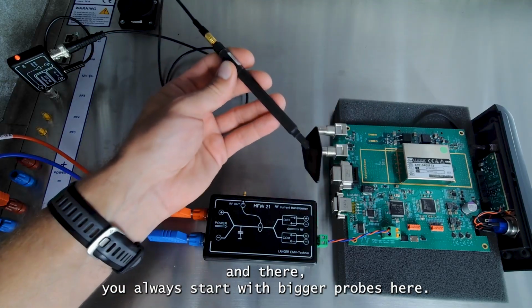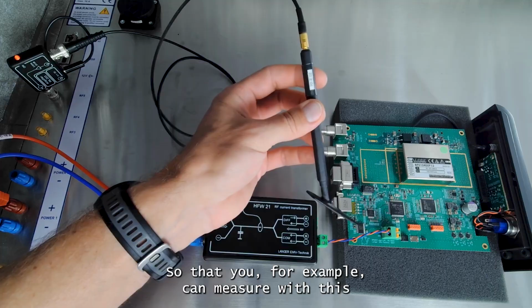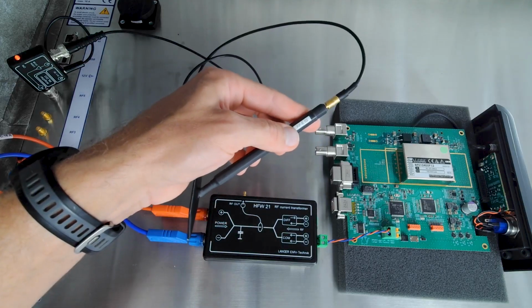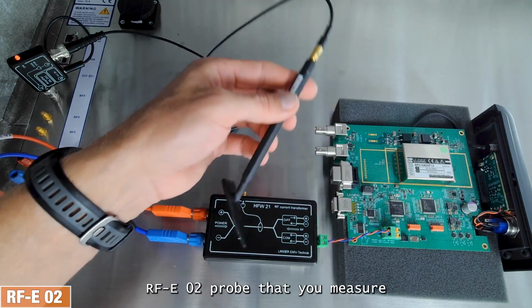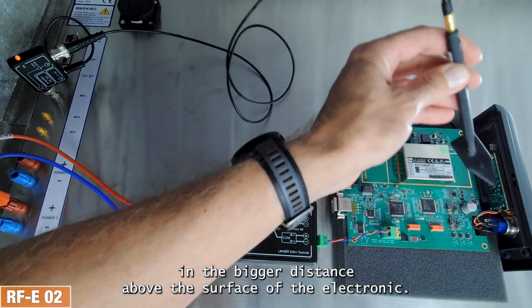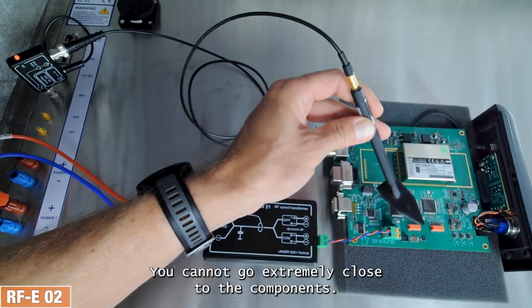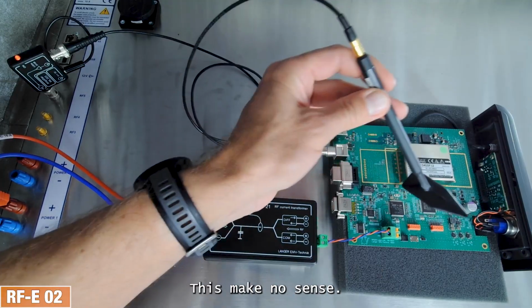And there you always start with bigger probes, so that you, for example, can measure with this RFE02 probe in a bigger distance above the surface of the electronic. You cannot go extremely close to the components, this makes no sense.